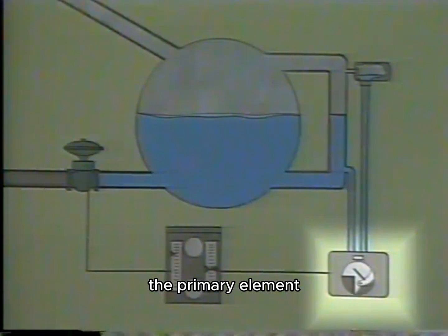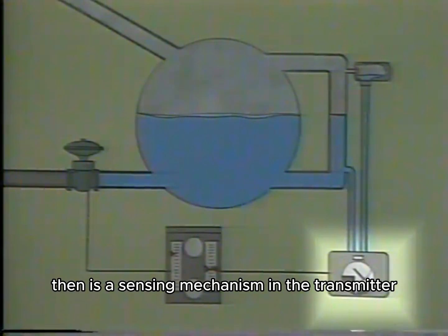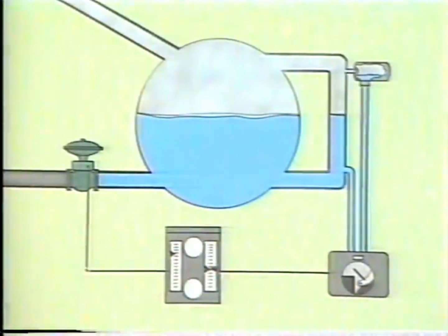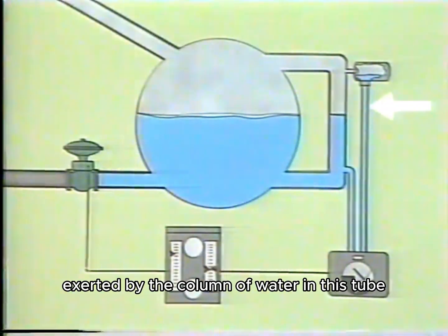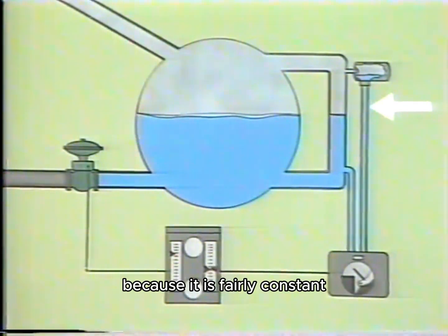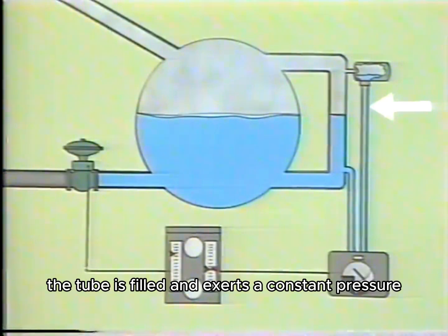In this control loop, the transmitter functions as both the primary and measuring elements. The primary element, then, is a sensing mechanism in the transmitter which senses the pressure exerted by the columns of water in both tubes. The pressure exerted by the column of water in this tube is used as a reference pressure because it is fairly constant. The tube is filled and exerts a constant pressure.